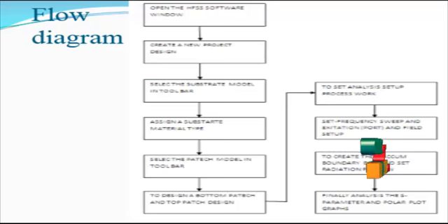These are applied over the frequency range. Then we set the start and stop frequency and the solution frequency. The solution frequency is changed based on the antenna model design, covering the full bandwidth with the center frequency for our required solution frequency. Then we set up all the frequency models and run the overall process.